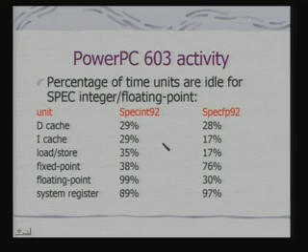Now, you see how the percentage of time these units are idle varies. The most glaring example is this one. When you are doing an integer computation, 99% of the time your floating point ALU and registers will be unused. And if you put the power completely off, if you do the VDD off to this part, then your leakage current is definitely minimized.